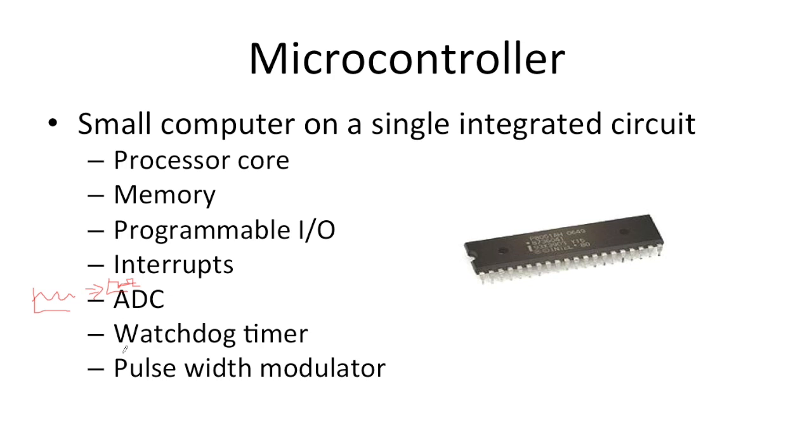The watchdog timer is a mechanism that allows the microcontroller to recover from programs which halt unexpectedly. So the idea here is that in the course of its operation, a program is periodically required to reset the watchdog timer, and in case it does not happen because maybe the program has frozen, then a timeout occurs and the watchdog timer resets the microcontroller so that the execution of the instructions resumes at the very first line of the program.